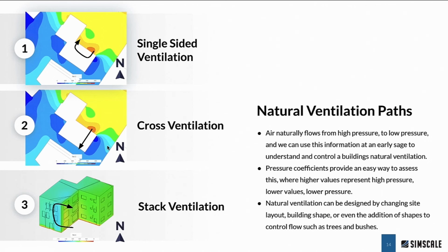And finally, stack ventilation. Now this is going to be, of course, enhanced by the buoyancy effect, but in this case, you can actually see that there's a higher pressure at the bottom of the building, lower pressure at the top, due to complicated flow patterns around that building, and therefore it's going to add to that stack effect even more.